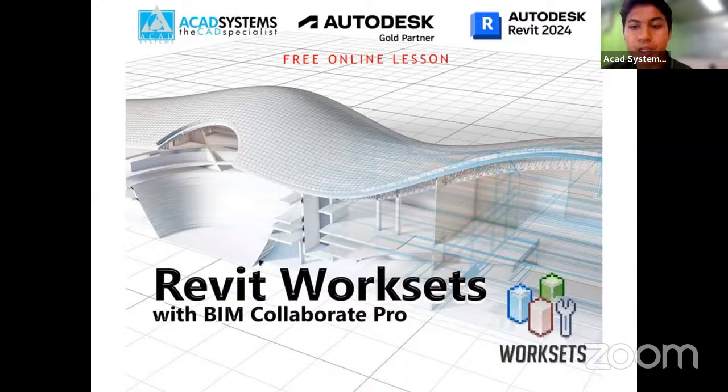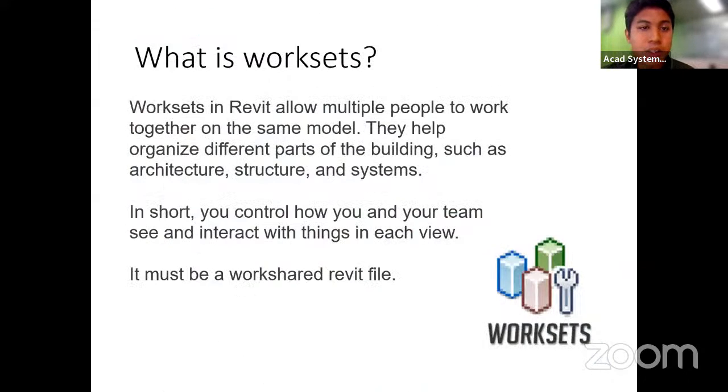For today's topic, I'll be talking about Revit Worksets. First, let's take a look at the terminology, what does workset mean in Revit. Worksets in Revit allow multiple people to work together on the same model. They help organize different parts of the building, such as architecture, structure, and system. That's just how they can categorize it. In short, you control how you and your team see and interact with things in each view.